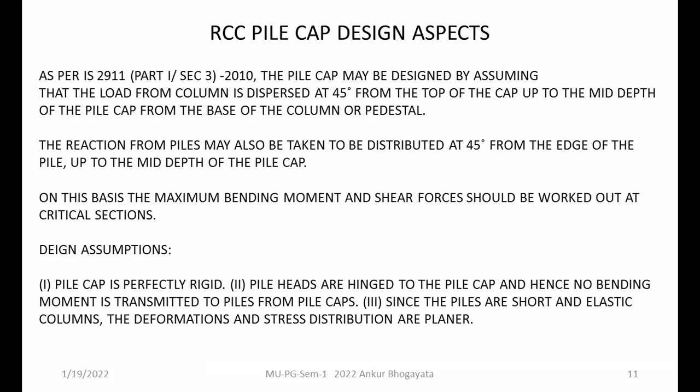Pile cap is perfectly rigid. That is the first assumption. Second is the pile heads are hinged to the pile cap, and hence no bending moment is transferred to the pile from the pile cap. Now, this is a very important assumption. You would have an argument that, sir, we cast everything together, and how can we assume that it's not rigid as a connection? As an element, it is rigid. That means it doesn't allow any sort of flexural or elastic properties within the pedestal itself.